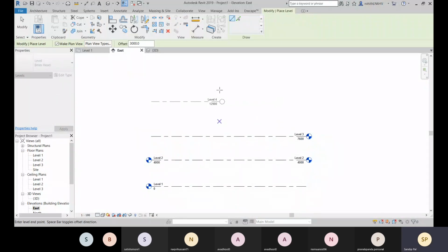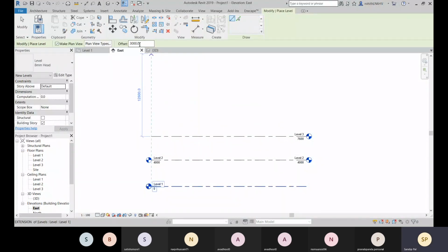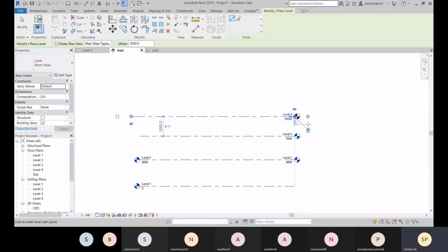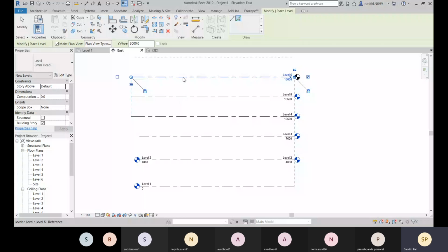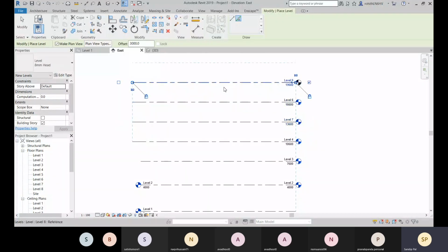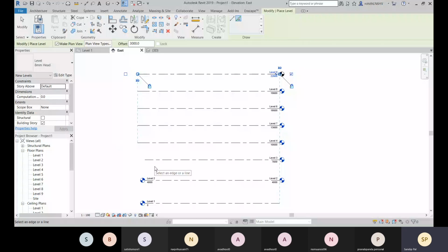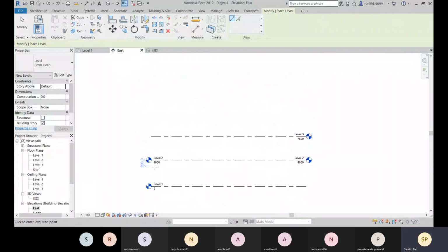Okay, from this point, just a second. On this line, this offset is available here. So from this, you can start it and align it. Like this also you can create it. And the best option is this pick line option. You can put this value and simply pick it and you will be creating it. This way it will be faster for you to create some levels. Now let me undo it.